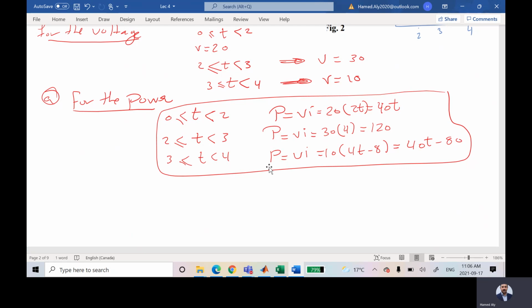At the end, I'll have a specific value, which is negative 60t plus 20. Find the integral of that. So yeah, that's the pretext to what I wanted to get to. On the graph of power, you would have positive and negative sections. So if in that circuit you had dissipated, say, 100 positive watts and then another 100 negative ones, would the integral of that be 0, even though 200 watts have been dissipated? If you have positive P and negative P and they are equal, the integral is equal to 0.